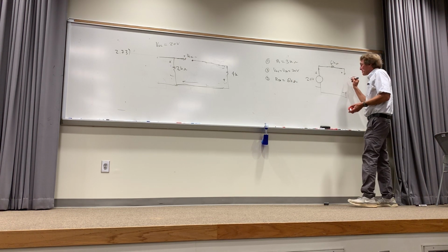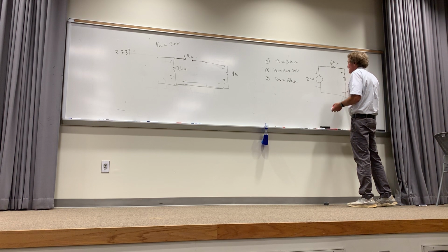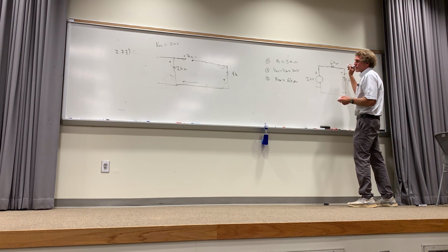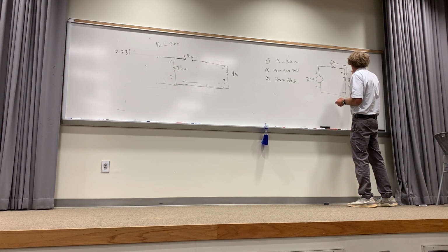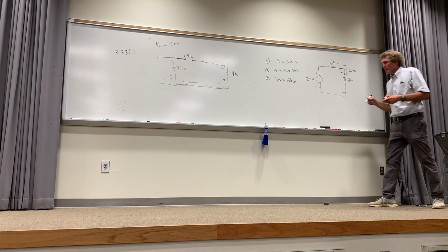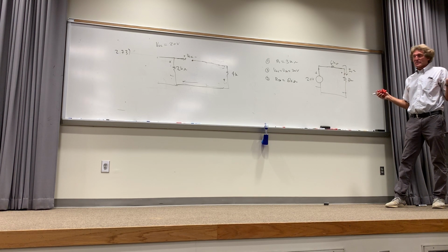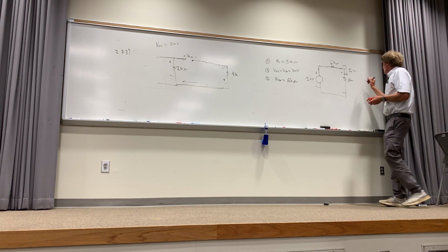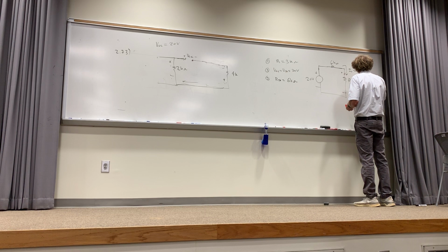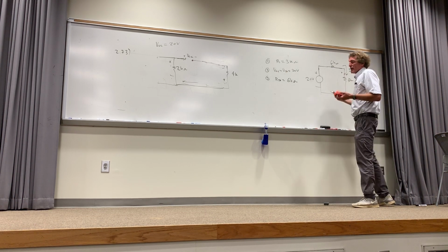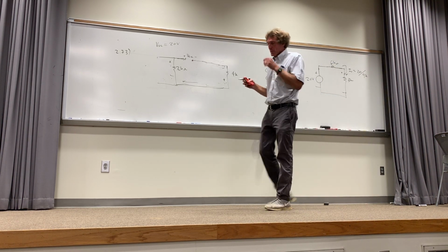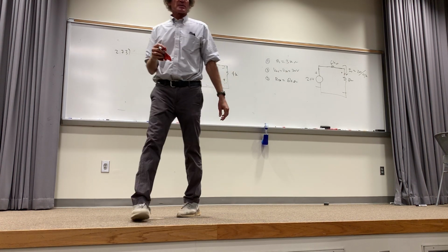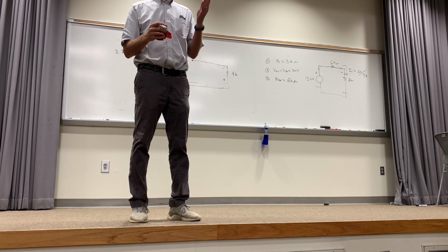And what is the load? Well, the load was 3K. And now did he want the current? He wanted the current. So what would the current be through that 3K by inspection? It would be 20 divided by 9K. Do you agree with me, class? Show of hands. You see it? So it'd be 20 over 9K ohms, and that's really it. It's a little over 2 milliamps, just a shade over 2 milliamps.